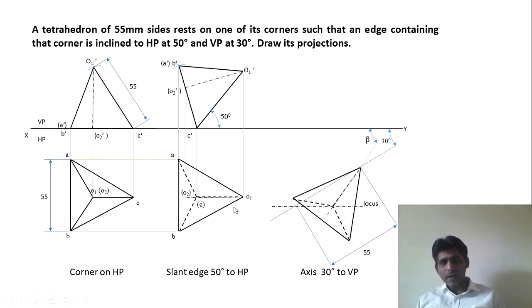At the same time we can mark O1B also here, and we can then measure this from here, that is CA or O2A. From this point you can mark and cut an arc here, and at the same time cut the arc here also. So you will obtain these 2 points, join these lines, and redraw the same thing here.